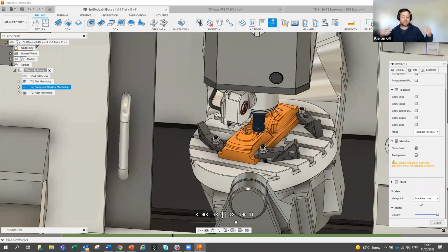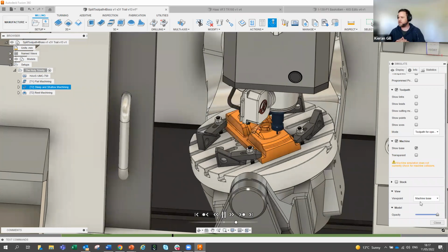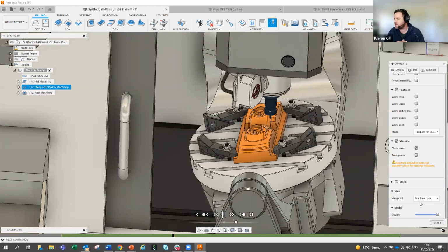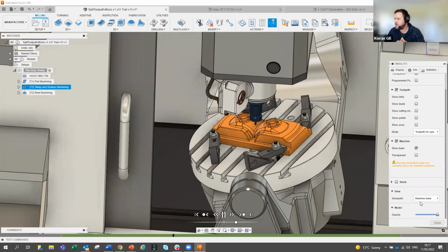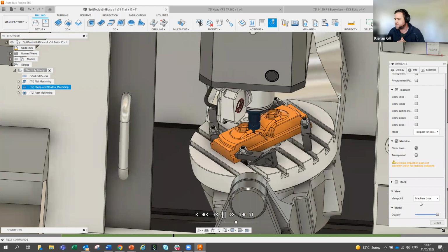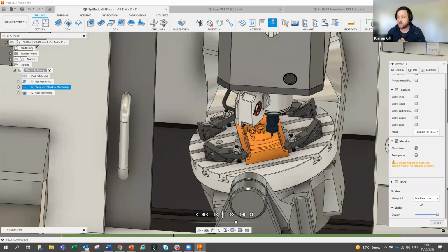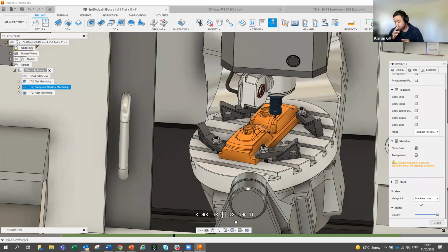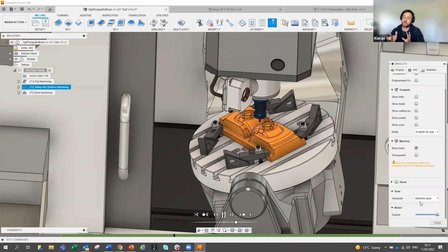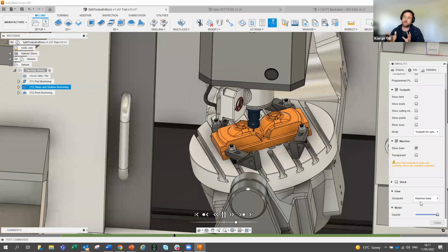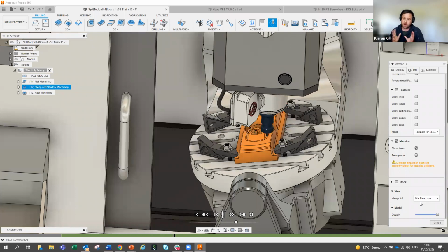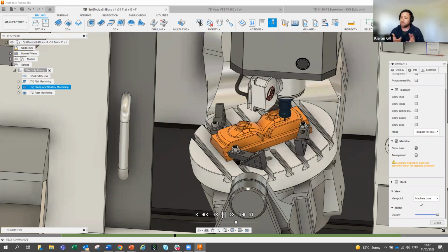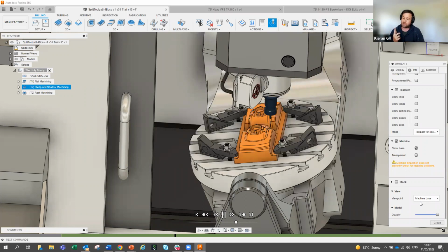Now, some things to bear in mind. Stuart said, for example, when I set X at 420, this ends up in my Z limits in the machine file. This is probably a setup issue. Whenever you're setting up, your machine always needs to be positioned in the home orientation first, as a general guide, and the Z-axis should always be pointing up.